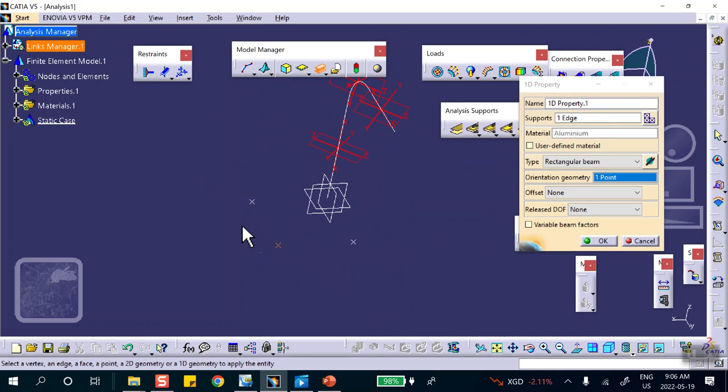The point is that if your cross section is not a circle or a tube, you've got to put some time into this. These are not hard. It's just that I'm telling you that it matters and you can't close it. And it's important because an I-beam that is on this roof is in a very specific orientation. That's the whole purpose of the I-beam, to use it in that orientation. Don't turn it 90 degrees. Okay? Any questions here?